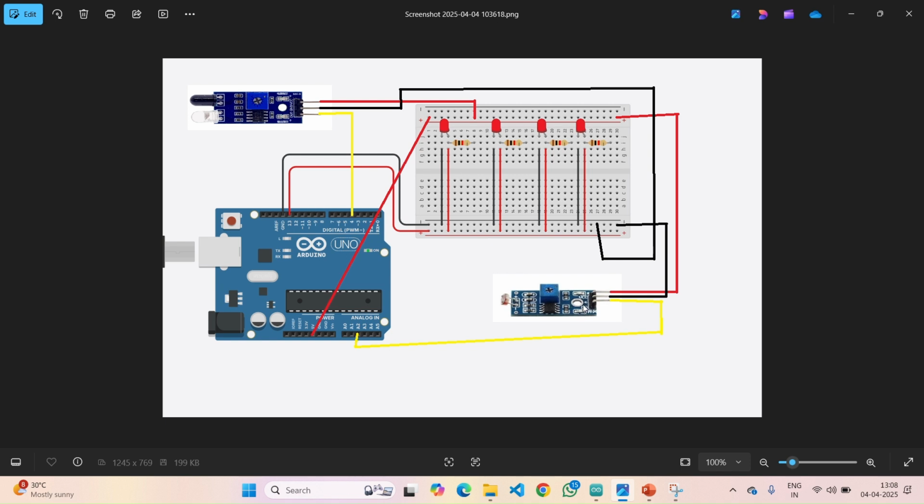And coming to the out of both the sensors, it can be given directly, or we can also use a third party connection, but I have given a direct connection. It is not an issue. For IR, since it is a digital sensor, I have given digital pin 4. For LDR, since it is an analog sensor, I have given analog pin A2. First, understand this connection, because my code and what I have executed will be different, because I do not have this many resistors and LEDs. That is the simple one, but while implementing the application, you need to follow this way of structure.